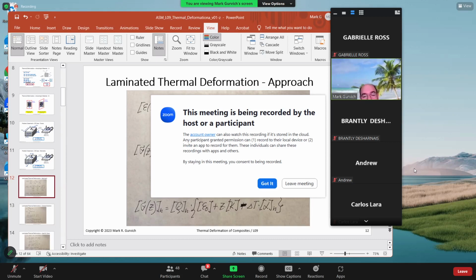we know if we multiply strains, and this entire portion is strains, by the stiffness matrix of a specific layer, we can calculate stress, yes? It's Hooke's law, nothing more. So here it's the stiffness matrix of a layer with number n, shown as Q, sometimes we use C, similar with stiffness, sometimes Q, sometimes it's the same definition. But actually, we multiply the stiffness matrix of each layer by strain, and this individual layer is defined by this formula.